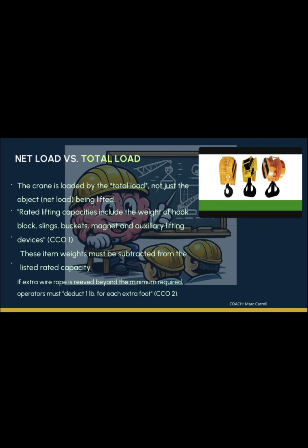The shaded areas, the capacities above the bold line on load charts, represent structural integrity. Those limits are based purely on the physical strength of the crane's components, hydraulic limits or rope strength, and not on overturning forces. We always base it on structural stability. How capable is your boom to support the load?